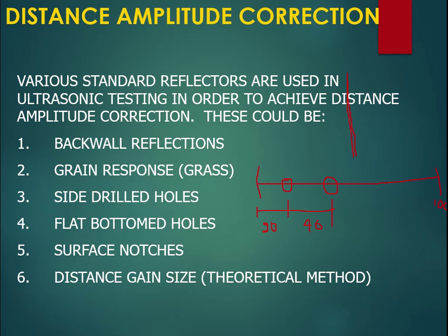When the sound travels in the material, some of the sound gets reflected due to the discontinuity, some of the sound gets scattered, and when it travels through the material, some percentage of sound gets attenuated or maybe absorbed. As the distance increases, the loss of energy also increases.